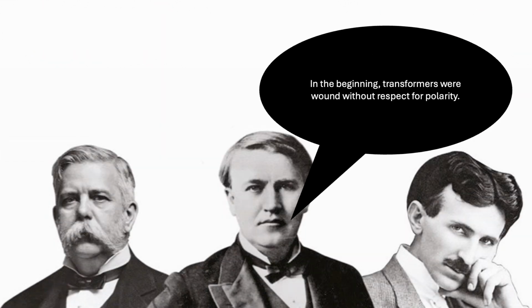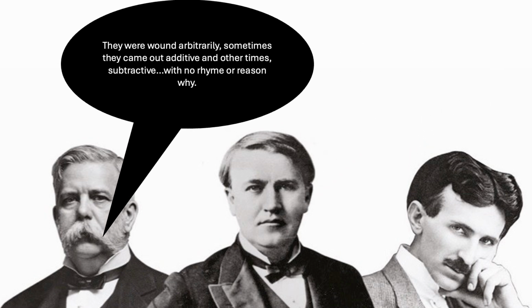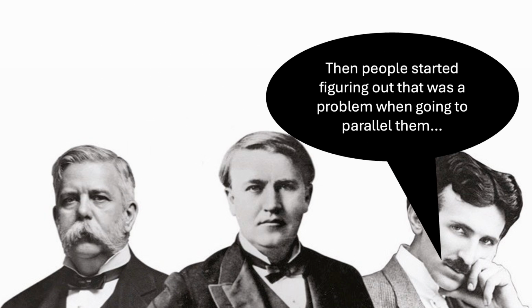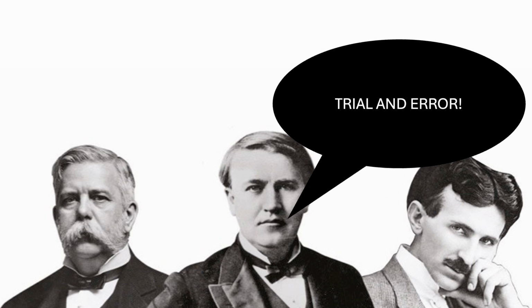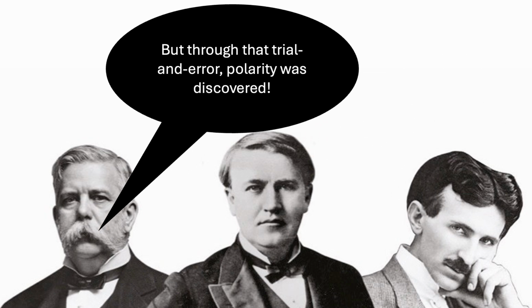Well, in the beginning, transformers were wound without respect for polarity. Sometimes they came out additive, other times they came out subtractive. There wasn't a rhyme or reason in their manufacturing. But people started figuring out that was a problem when going to parallel them or use them in banks. If the polarities of the secondary bushings didn't match up, then stuff started blowing up. But that was the process, trial and error, figuring things out.